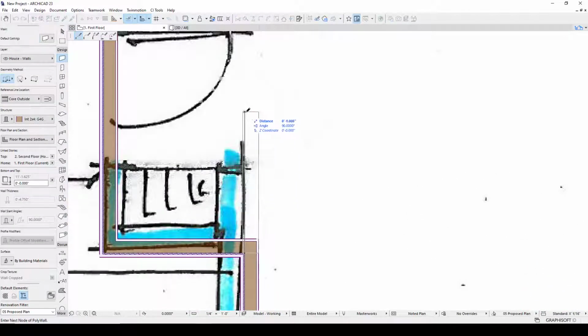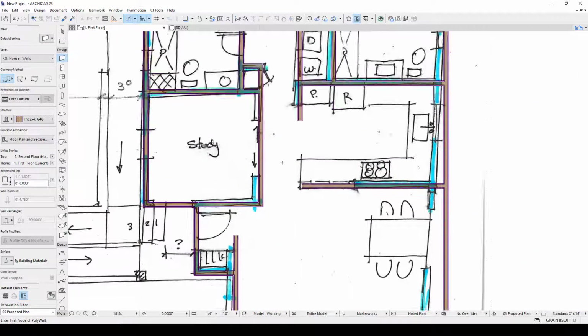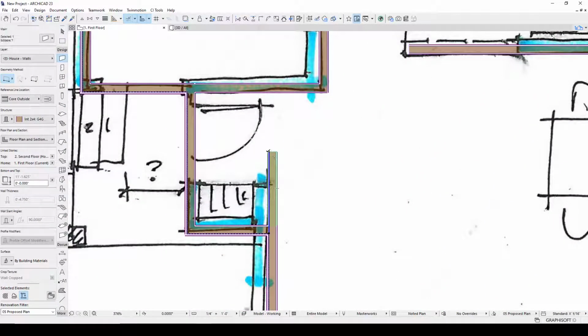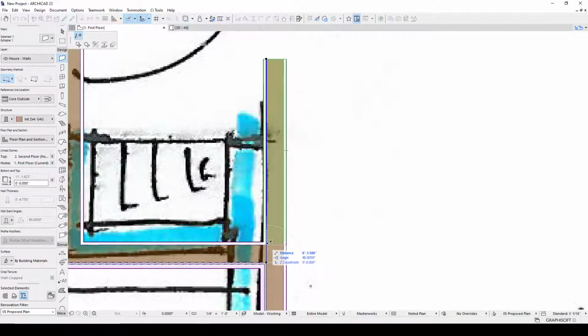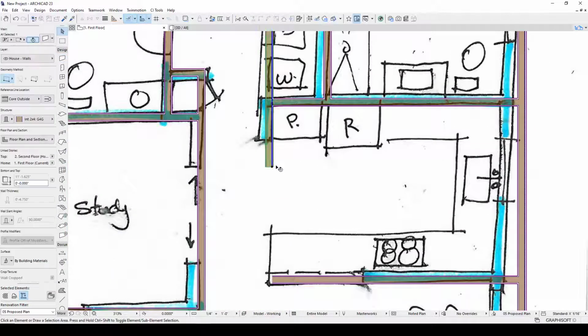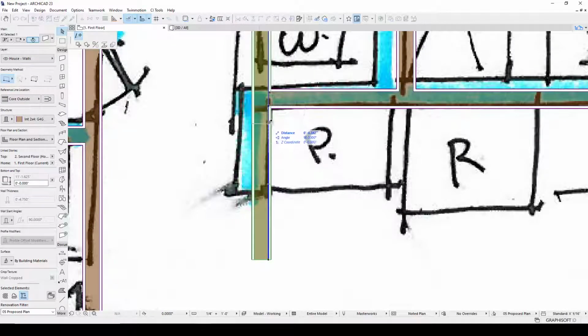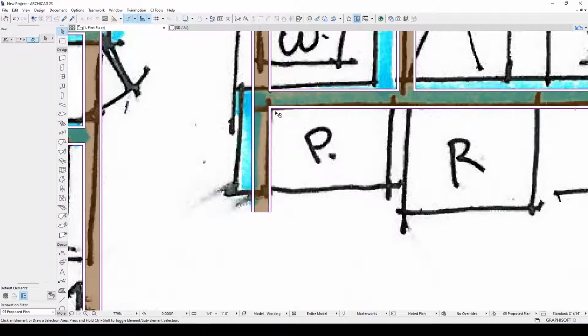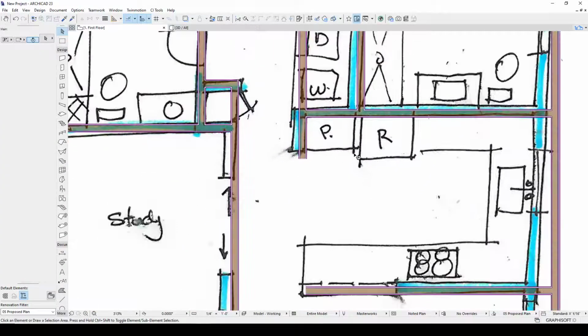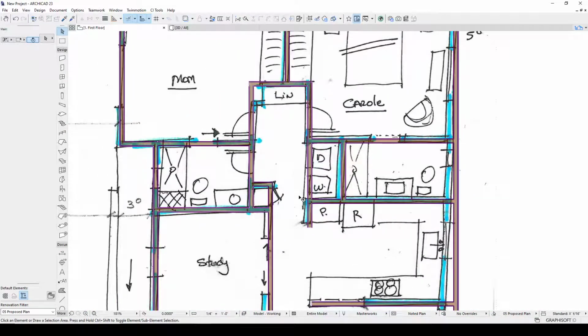Interior wall here, bring this up, run it a little past. Then we can decide what this is. So I'm going to make this from this point 2'3". Here, I'm going to make this 26 inches from that corner. Notice lots of moving my origin. It's one of the really wonderful tools that ArchiCAD allows.